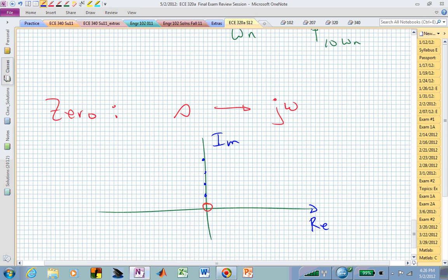to find the frequency response. And from this point, if I look at the angle from this point to that 0, it's 90 degrees. Actually, it's really from this guy up to that point, so that's 90 degrees. This guy still at this point looks up there, and that's 90 degrees. So every time you're looking at 90 degrees, and because it's a 0, it's upstairs, it gives you 90 degrees. It doesn't matter where you are on that imaginary axis. A 0 at the origin contributes 90 degrees.